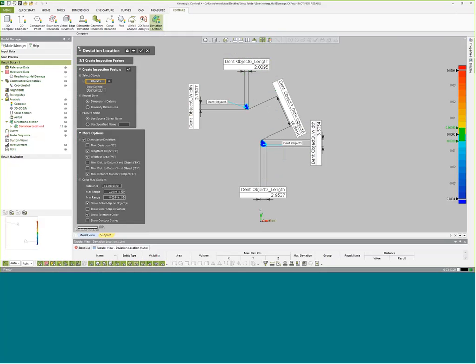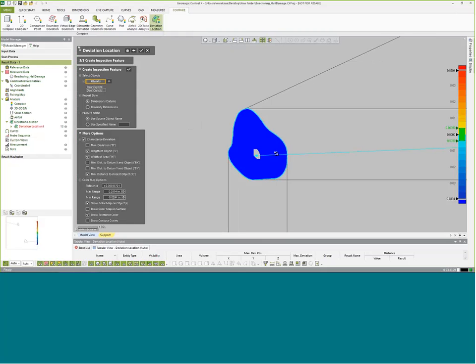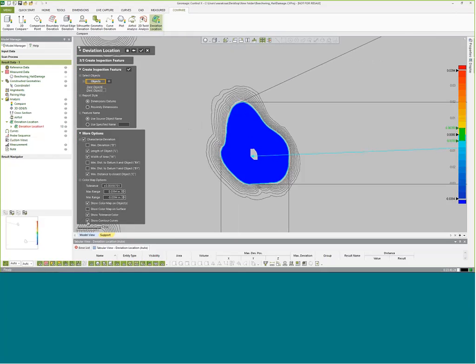We could also just show color maps on objects if we wanted to really zoom in on something. We could also show contour curves of the distances surrounding the object as they dive in. And you can see that our min and max range here is probably a little too low for these. So let's turn this up. I'll make this a quarter here. And we'll make this one minus quarter. Having typing issues, apparently. And then we can see our contour lines better on our part and what's going on with our stuff here if we wanted to do that as an investigation.